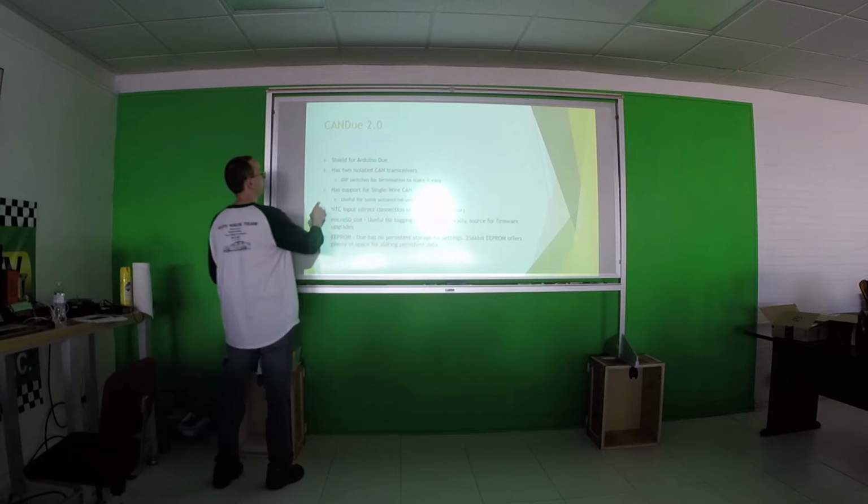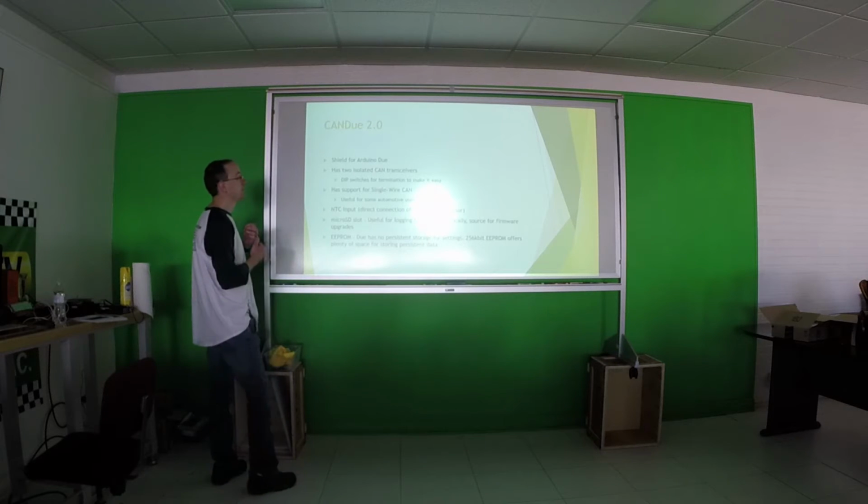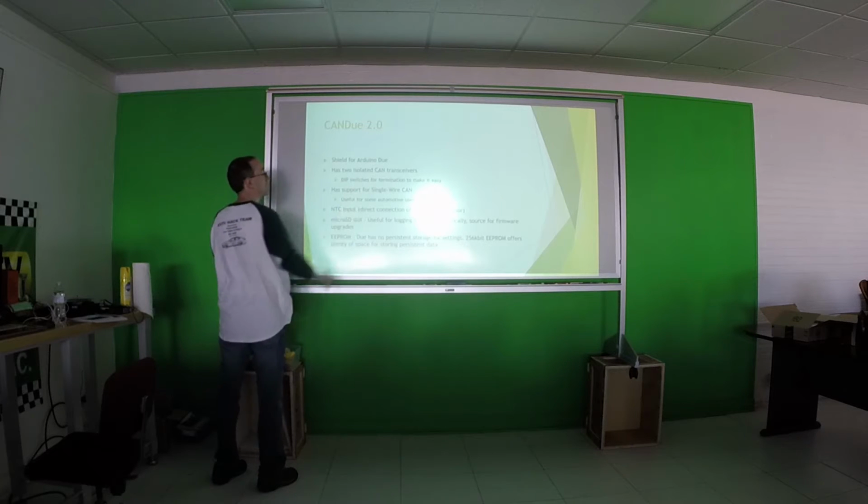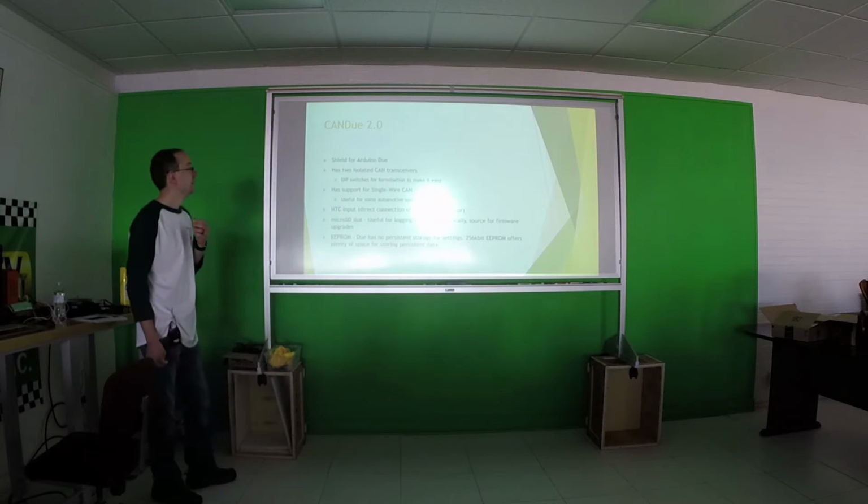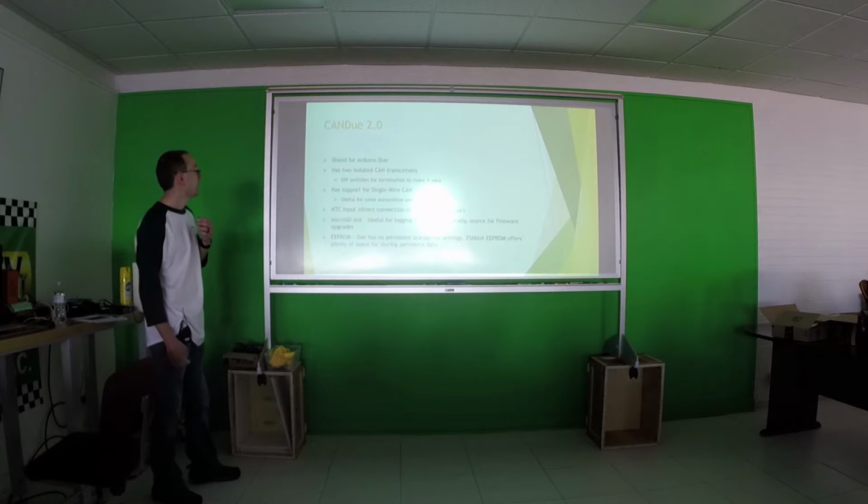Actually, as well, one of the things a lot of the cheaper boards that you can buy do not have are isolated CAN bus transceivers, but this does. The advantage in isolated transceivers is that noisiness on the CAN bus doesn't backfeed through into your laptop and blow anything up. So that's kind of handy.